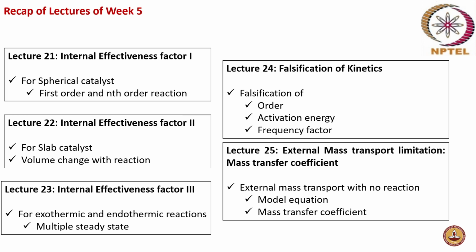In the first lecture, the internal effectiveness factor for a spherical catalyst was derived, for both a first order reaction and an nth order reaction. It was found that when the Thiele modulus is very small, the effectiveness factor is almost constant, and in this region surface reaction control dominates.